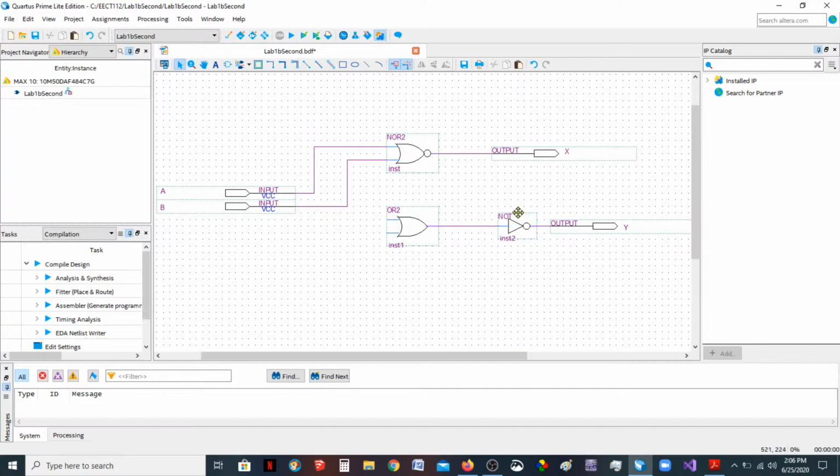Okay. So that should indicate that you have 2 things connected there. All right. So now one of the inputs of this is going to be A, so watch how I make the connection. I'm just going to go from here, click, drag, and make sure you go all the way through the B. You don't want to make 2 connections here. So I go up. There we go. So there, I see the junction. It gives you a junction when you have more than 2 things connected. And then the other one, I'm going to pull right up to here.